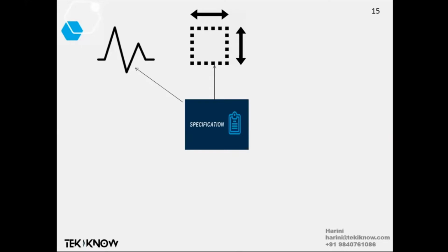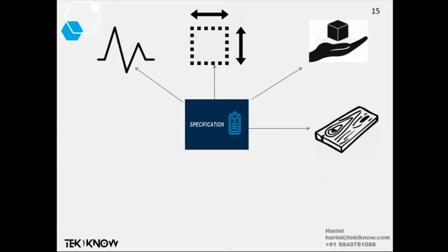Because in this world there are lots and lots of types of antenna. You can design a horn antenna at 2.45, and also a PCB antenna at 2.45, and a sheet antenna or wire antenna or dipole antenna, many kinds of antenna at a single frequency. So first you have to fix what kind of antenna, what space is available to place an antenna, and size. That is what I said. Size and dimension are interrelated. And material, yeah, there is lots to say about material. It would take a day actually, because material selection is a very important thing.